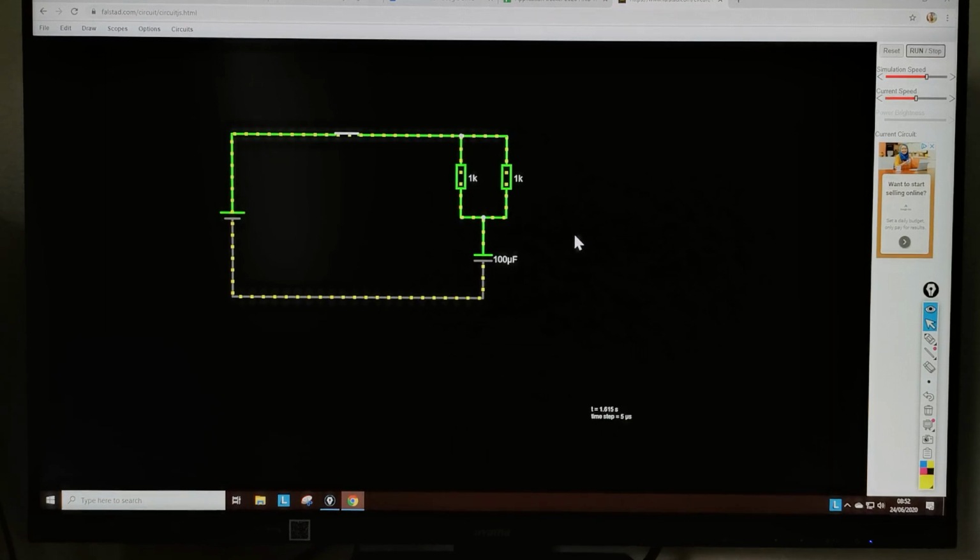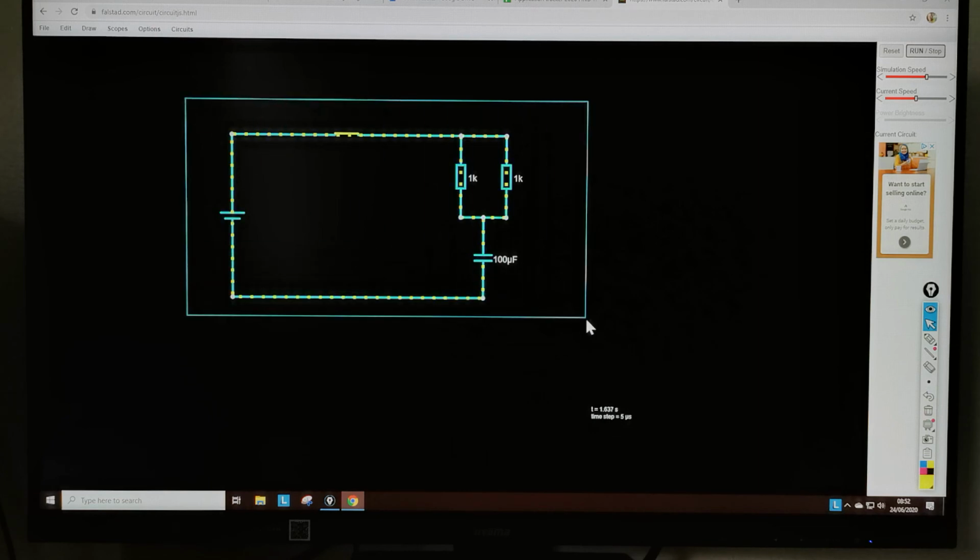Okay, let's delete that. Just draw a box around the whole thing, and we'll look at a simple AC circuit. So I'm going to press V again for a voltage source and drag up the way. W for a wire, top and bottom, and then R for our resistor. Simplest possible circuit. And I want this to be an AC circuit, alternating current rather than DC.